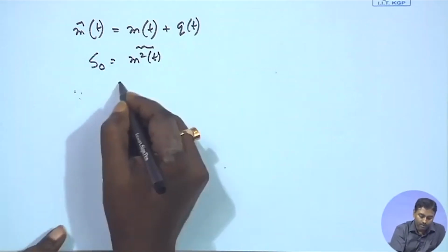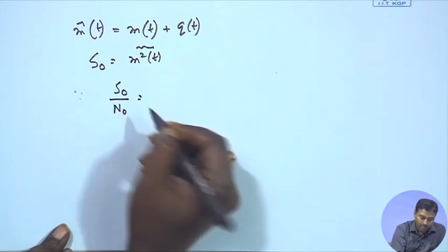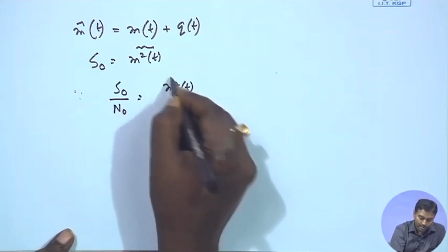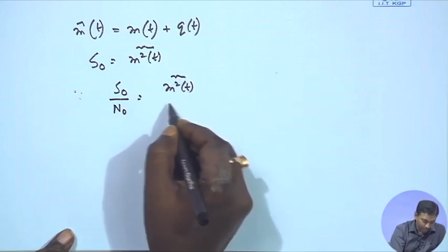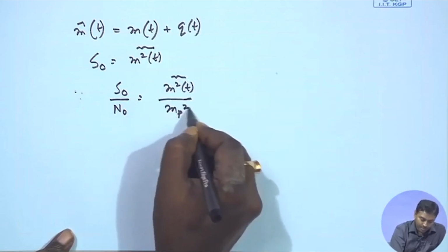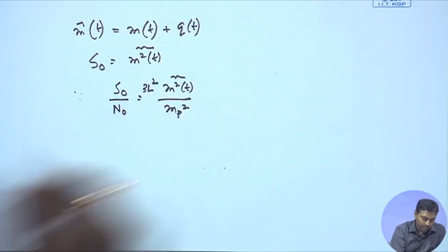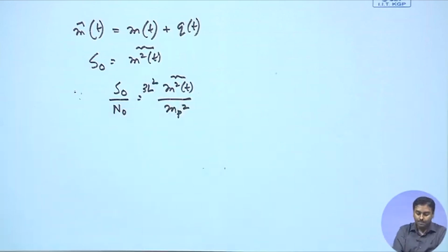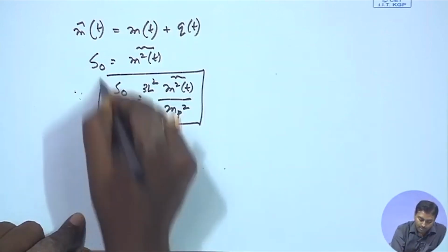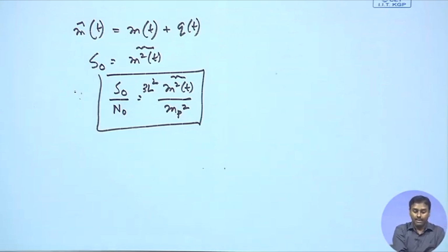Okay. So, what will be my signal to noise ratio? That should be that message signal's power divided by the noise, which is mp square by 3 L square, right. So, this is how the signal to noise ratio is calculated in a typical PCM transmitter receiver.